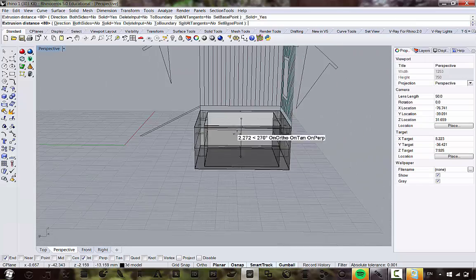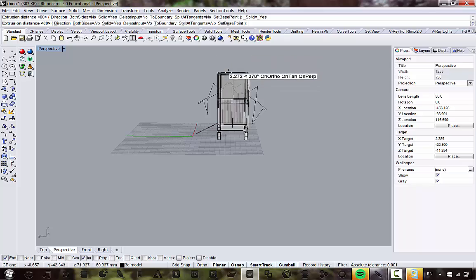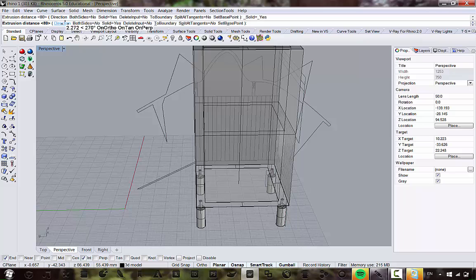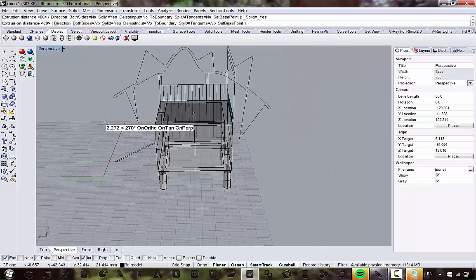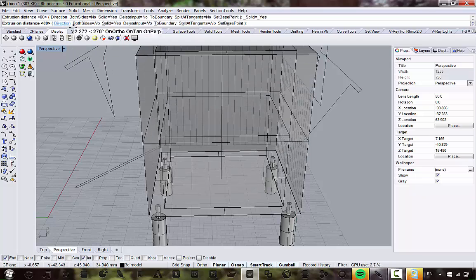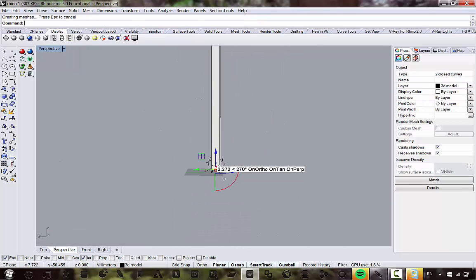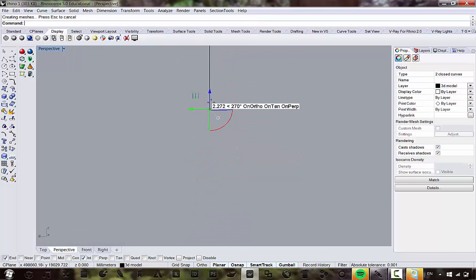And you can see what's happening is it's allowing us to drag out this three-dimensional object. Again, you can set things like direction. If you want to enter an actual numerical value, you can. You could even just type in right here. And you can also type in units in Rhino. We haven't really gone into units yet. But I could type, let's say, 200 meters, M for meters, hit enter. And this is 200 meters tall.